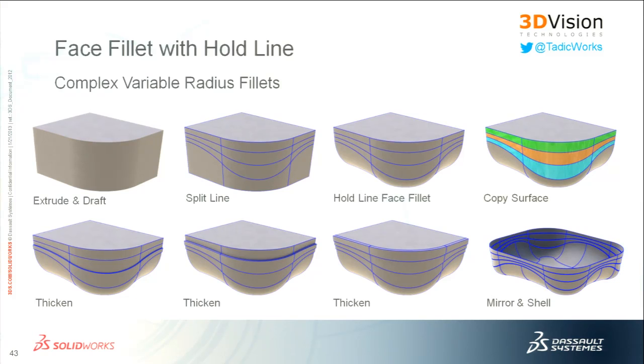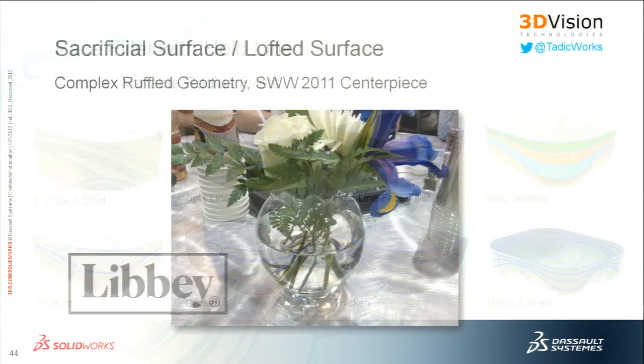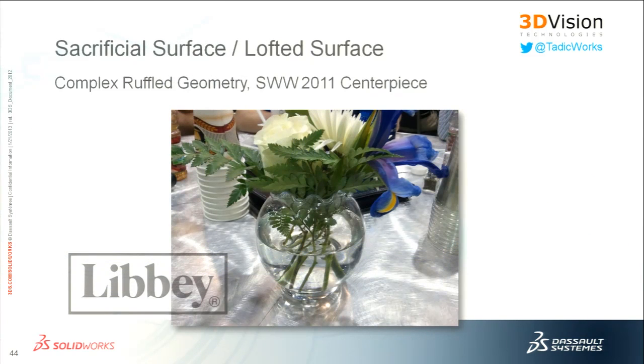And then the rest is just solid modeling tools. I go ahead and thicken or delete the face, or shell it out, I'm sorry, and then mirror it across and maybe revolve the lip that goes around the top edge.